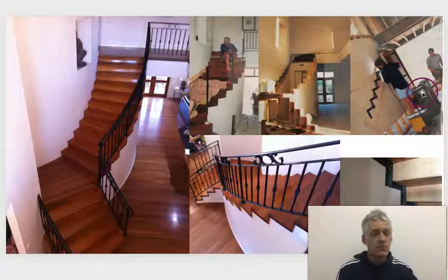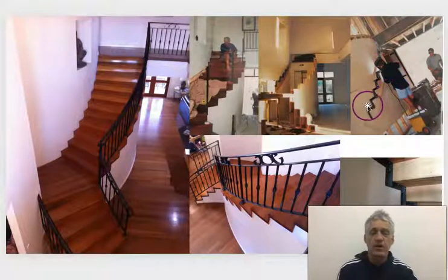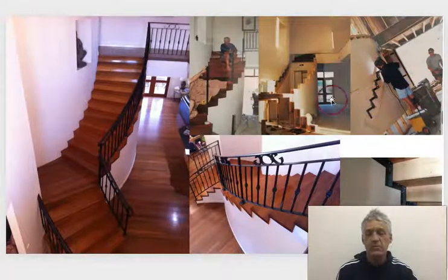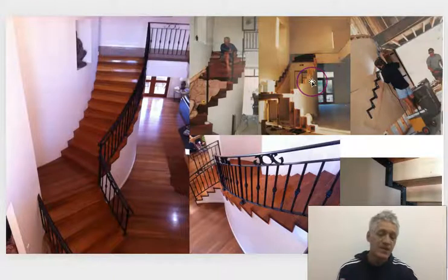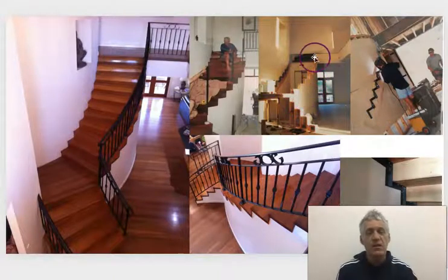We're using different tools and different materials. We had to sort out different ways of doing it because many people told us we couldn't do this, we couldn't build walls that are curved. But we just need to use different materials, and instead of using a 10 millimeter gyprock, we use 2 layers of 5 mil gyprock so we could bend it round.